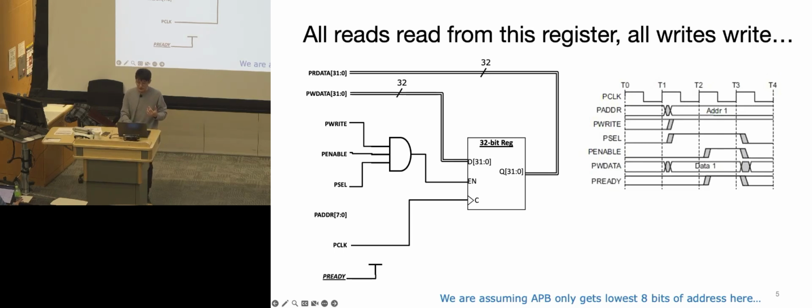The reason is that under a write instruction, any of these registers within a peripheral is only enabled under the following conditions. First, the p-enable is high, which is a signal sent from the requester to all the completers, or from master to all slaves, indicating that whatever data is currently on the bus is ready, so they can do whatever instructions need to be done for all the completers to know. The second is the p-write, which is more straightforward. Basically, if it's high, it indicates a write instruction. If it's low, it's a read.